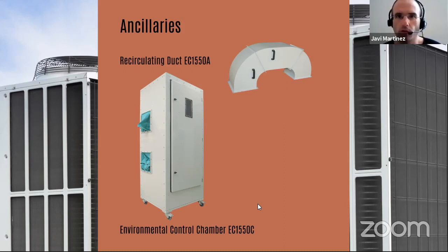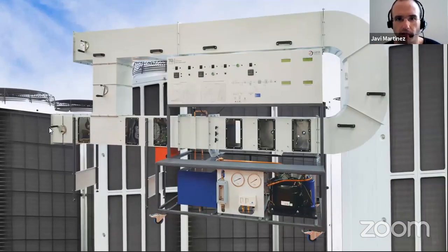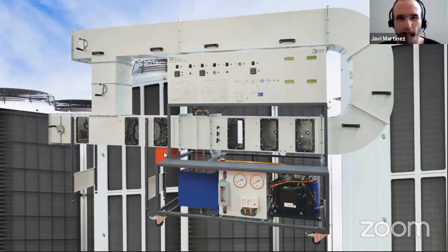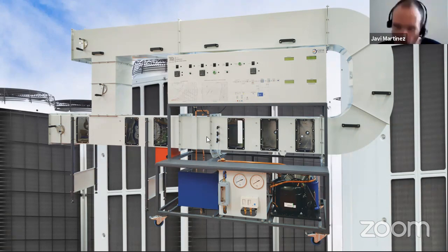Indeed, and we've got two different ways of controlling humidity. One is isothermal humidification via the steamer, which is this bit here, isn't it? No, that's the red box. Oh, okay, the red box. Apologies. Isothermal humidification, and the other one is adiabatic cooling, which is injecting water. That's the one, yes, injecting water into the airstream. So we've got two ways of controlling humidity, but the humidity is not controlled via PID. However, the heating is controlled via PID at both stages, the heating process and the reheating.